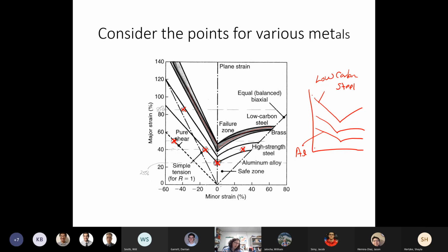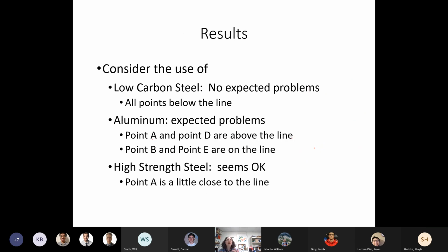There also were some challenges with the formability of aluminum. So you cannot just take the same stamping dies that you have been using for steel and use them on aluminum, because in some cases you may have way too much deformation. A lot of the work we're talking about was developed in response to that, looking at moving from steel to aluminum.